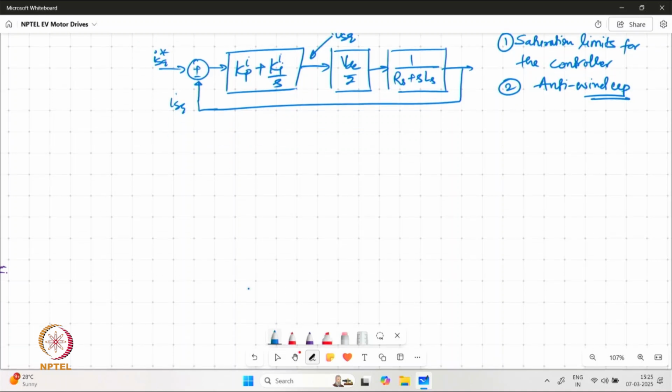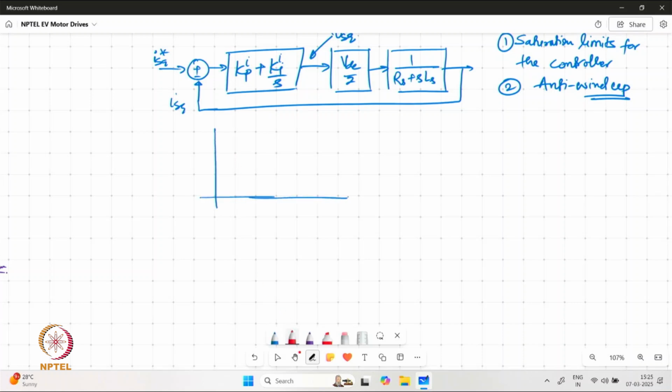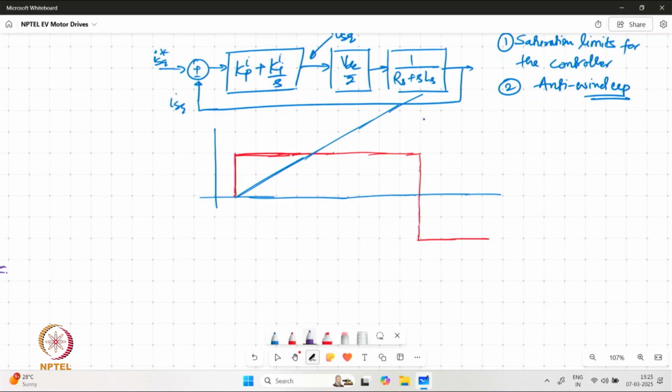So as we have previously discussed, if we have provided an error of a constant value, the integrator will have tendency to assume a very high value, and if meanwhile our error is changing its nature, the integrator is going to take a lot of time to return back to any value which will be useful for the negative error.